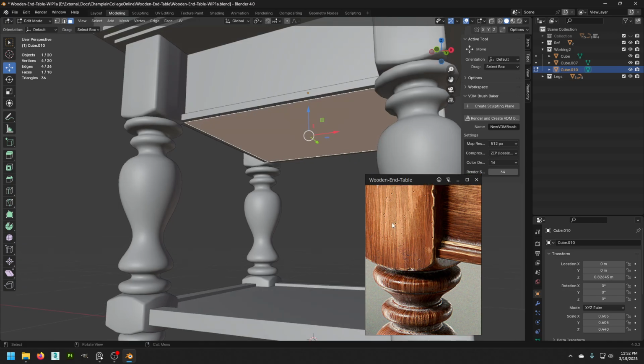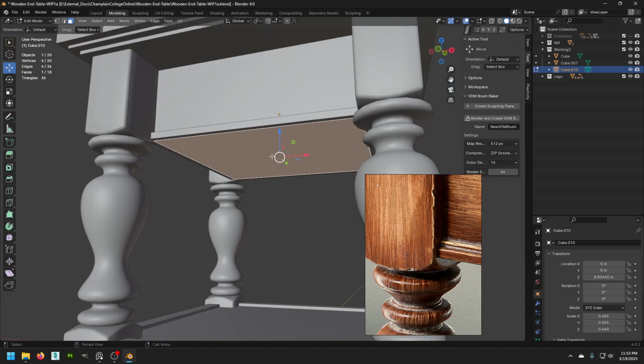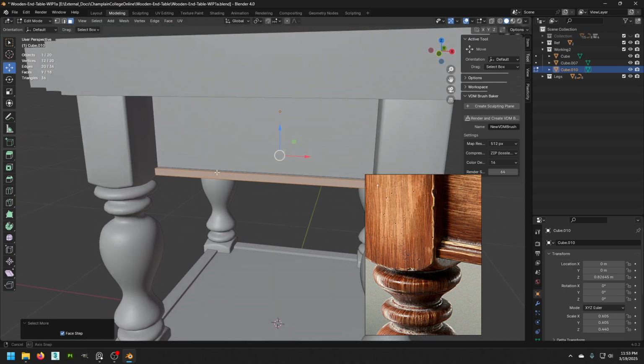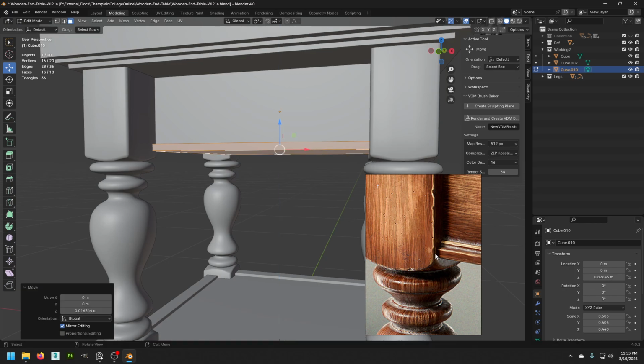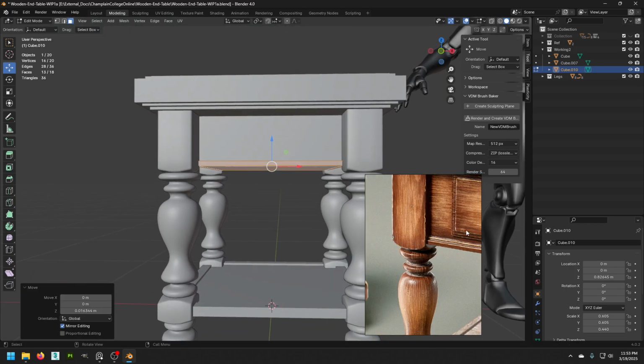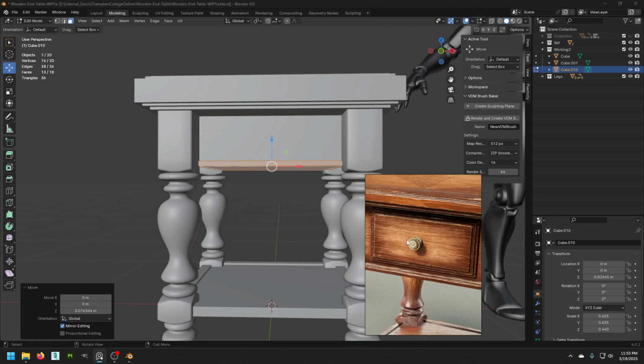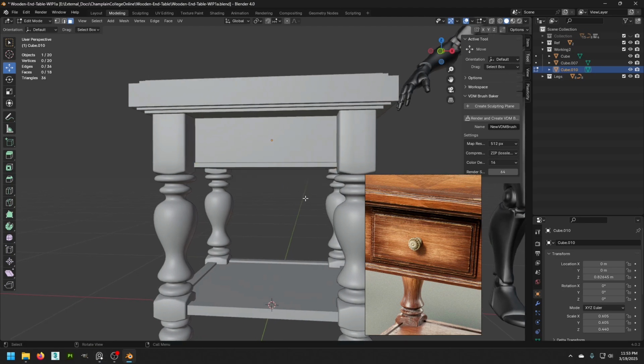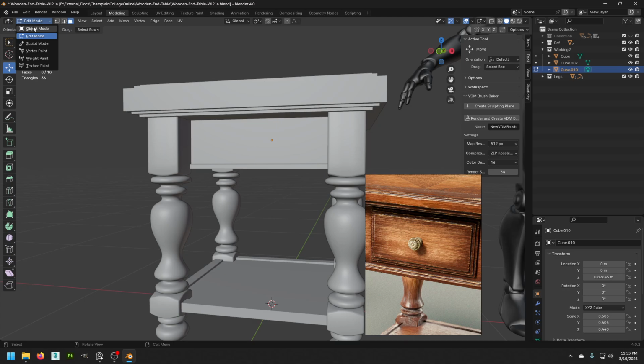So I want to do growing my selection. Here's another way to select things. If I select this and hold down Control and the plus button, this will grow my selection, and you can subtract your selection by doing Control plus the minus button. So you can do that additively and subtractively. With that, I'm just going to move this up a little bit so that it matches that. Okay, and then we will do a new box probably, and then a new cylinder to get the little handle in there. Okay, have that go back in.